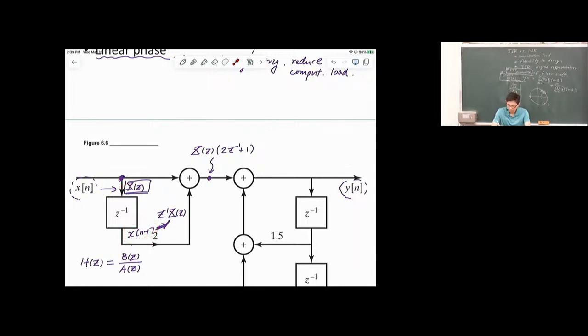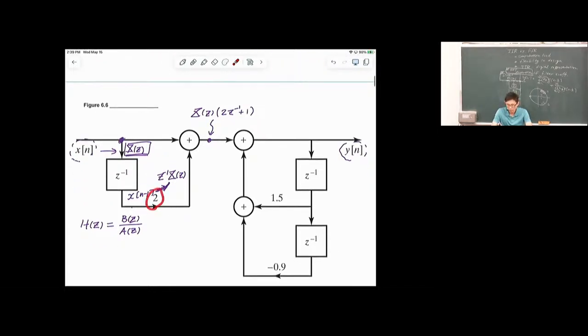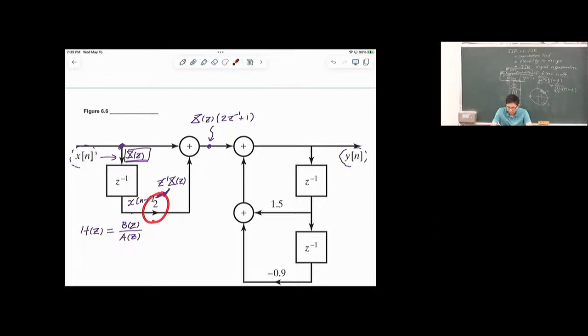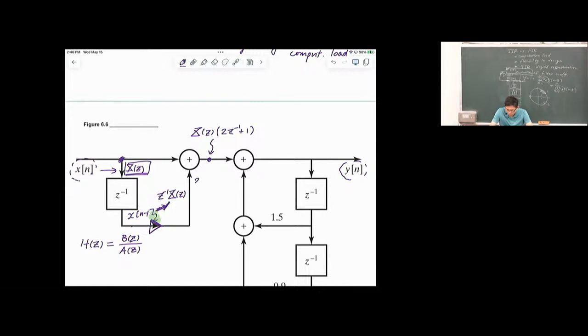And here, when we put a number next to an arrow, like here and here, that means to multiply the signal with that factor. Is that clear? Okay. So put a 2 around here. That means right here after multiplication, think of this as producing a gain of 2. Multiply the signal by a factor of 2. So here we have 2 times x n minus 1, and then